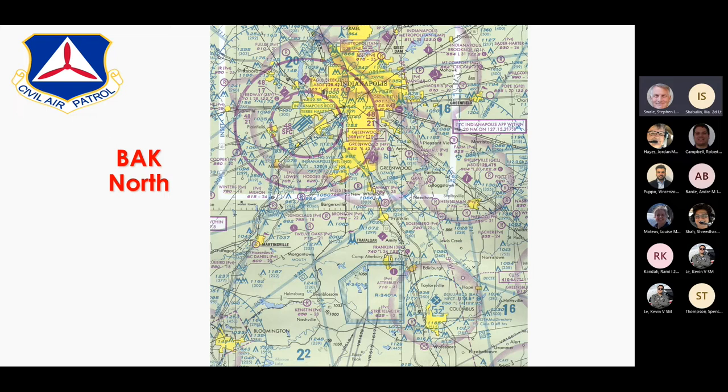It is on the controlling agency to cease firing if they identify an airplane that has wandered into their area. But, you know, I myself would not feel very comfortable flying into a controlled firing area unless I knew that it was cold by checking in with ATC that was controlling that area.